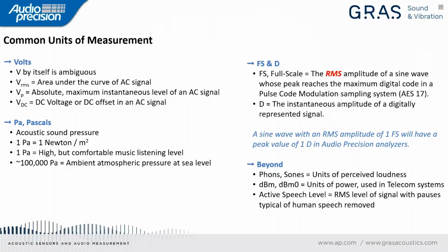But in fact, what's happening is sound is a small AC signal riding on top of a very, very high DC offset, which is the static atmospheric pressure. At sea level, roundabout, there's about 100,000 pascals of atmospheric pressure. And you can then work out that a pretty high AC signal in terms of sound is going to be really a small signal riding on top of that static pressure.